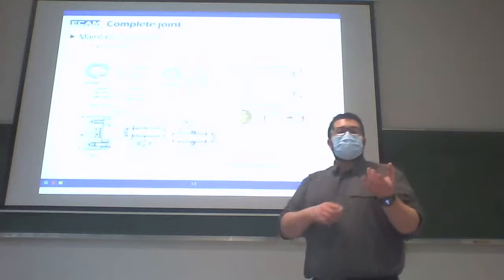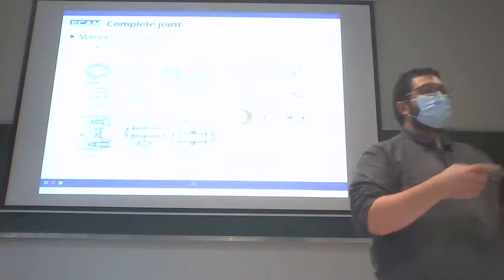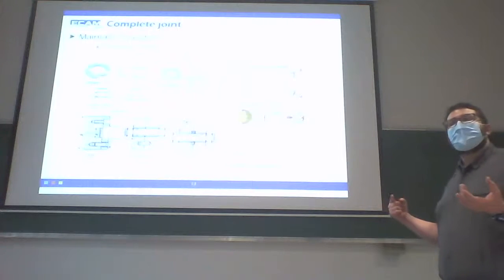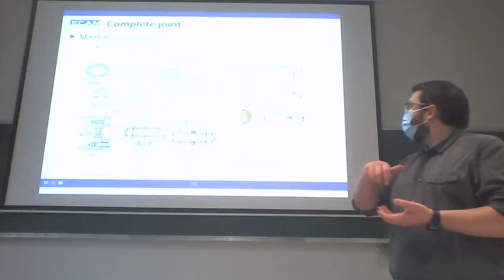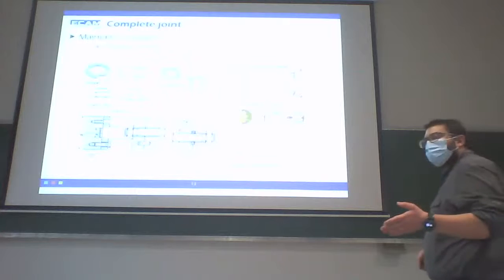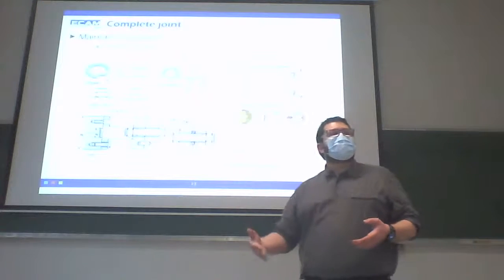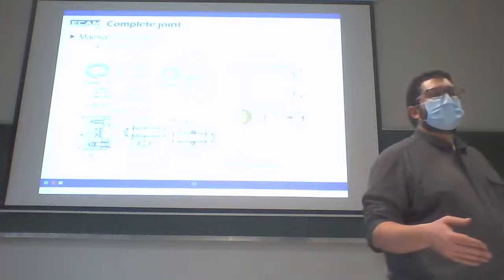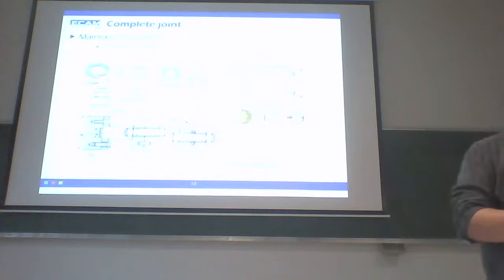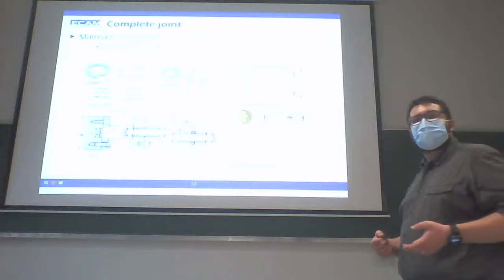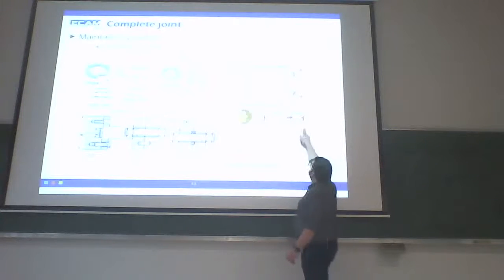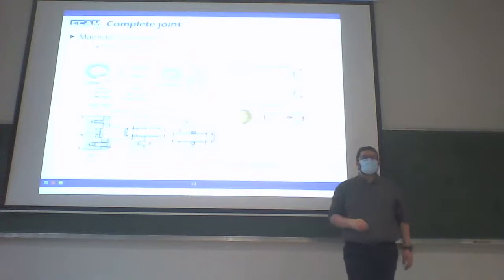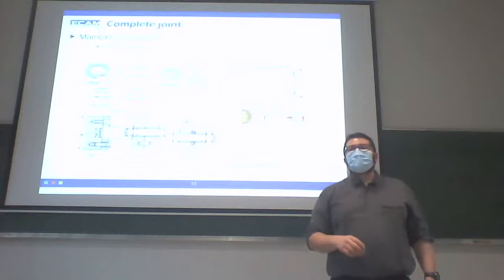We'll add different shapes like this on the nut, and inside the shaft we'll drill a through hole. When we screw the nut, we align the hole of the shaft with the shape of the nut. And between them, we'll put a split pin to stop the rotation of the nut. The split pin is in red, inside the shaft and the nut, to stop the rotation of the nut.